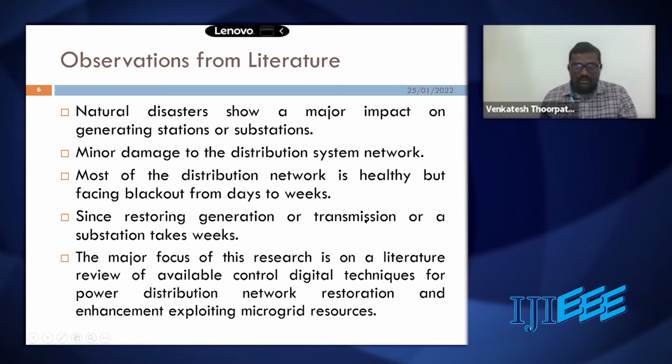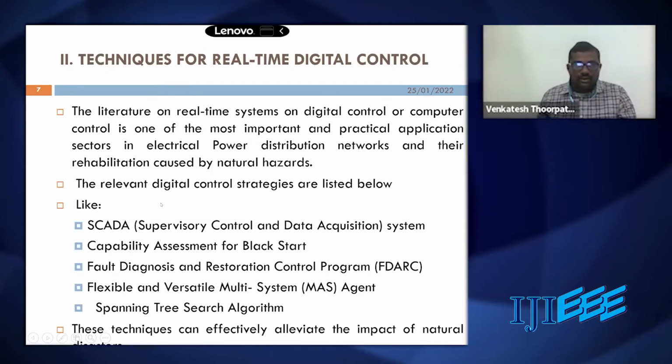Restoring generation, transmission and substations takes weeks. So the major focus of this research is to review the available control techniques. I have given some restoration techniques for the power distribution network: SCADA, capability assessment of black start, fault diagnosis and restoration control program, flexible and versatile agent, and spanning tree search algorithm. These are the techniques effectively used for restoring the power distribution network.